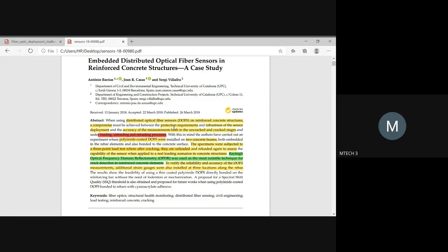By having some theoretical aspects, some measuring parameters through which they regularly measure and let you know, right? So, apart from doing this regular interval check, if you have these optical fiber sensors, this will easily help you identify even a single crack if it is formed on the wall. And hence, in theory, you have studied that optical fiber sensors are used for crack detection.